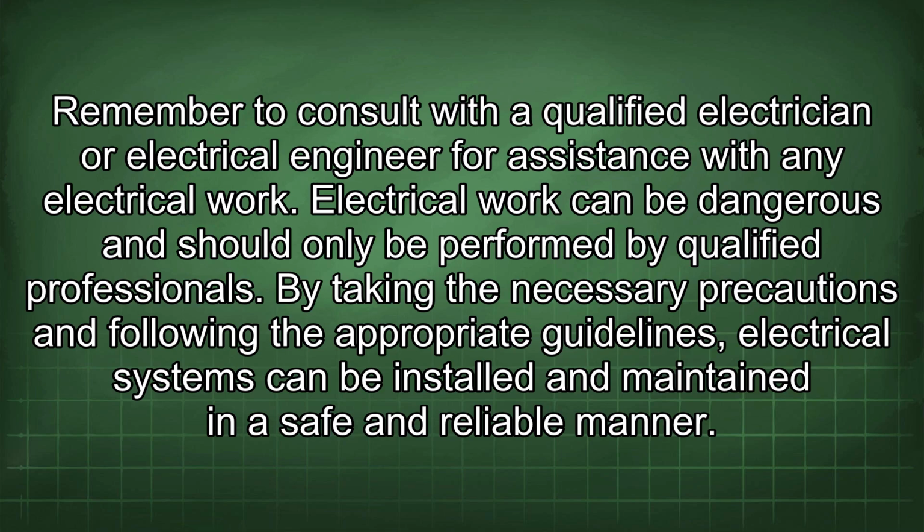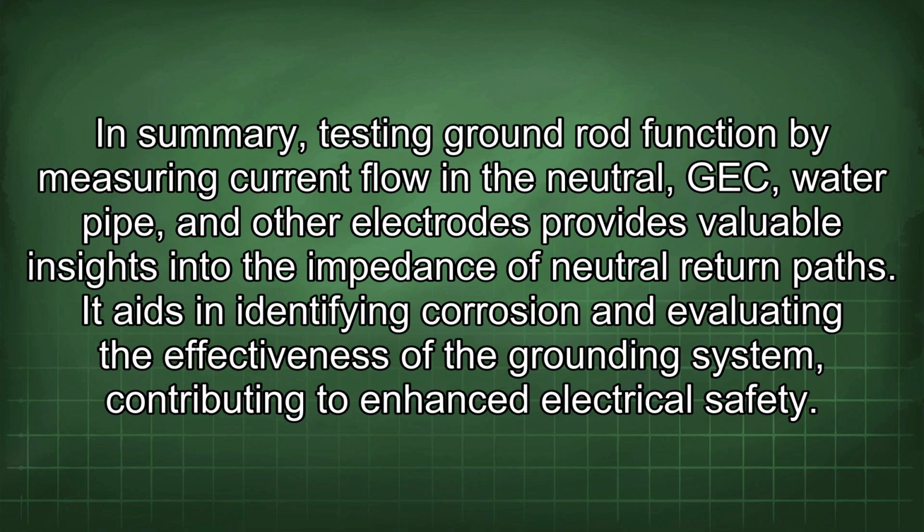In summary, testing ground rod function by measuring current flow in the neutral, GEC, water pipe, and other electrodes provides valuable insights into the impedance of neutral return paths. It aids in identifying corrosion and evaluating the effectiveness of the grounding system, contributing to enhanced electrical safety.